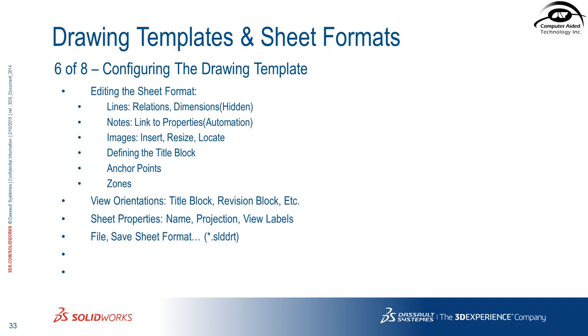So now that we've got it pretty much set up, it seems, question? I note there, in our company, we use first angle and third angle. Okay. Users will make multi-sheet drawings. So when they paste the sheet out of one drawing into another to combine sheets, you have to be real careful about first angle versus third angle, because if you carry over, sheet 2 can be first angle while sheet 1 can be third angle. Wow. If you copy and paste the sheet into another drawing. Just making engineers have to be even sharper than they already have to be with that system.